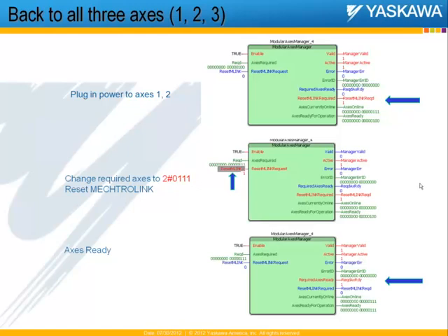There's another question about why valid is off in the second Axis Manager function block there. When reset Mechatrolink is being executed, the status of the axes that are online, or the status of parameter 1330, may not be true, because reset Mechatrolink is basically soft rebooting all the drives that are on the network. So we do not want the function block to be showing a valid output, because the outputs there may not be valid while reset Mechatrolink is being run inside the function block.